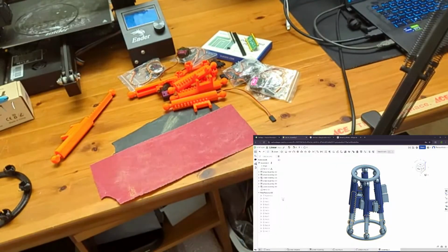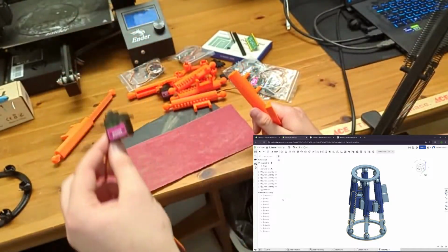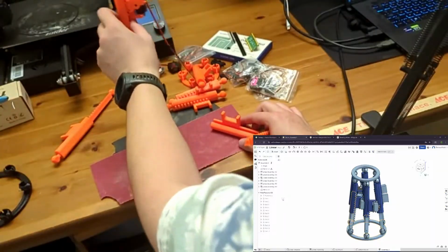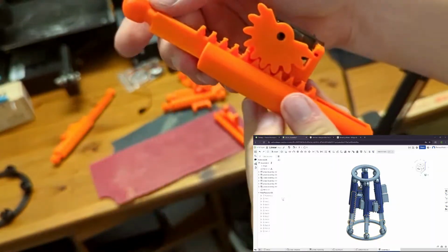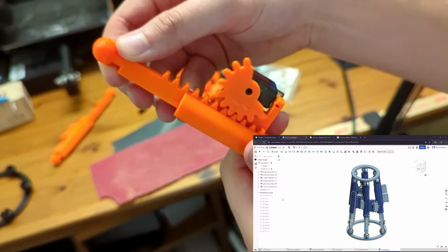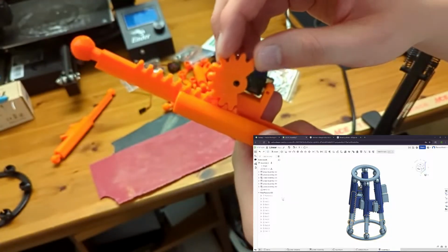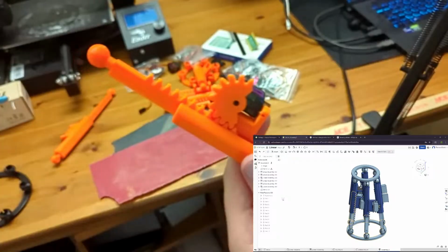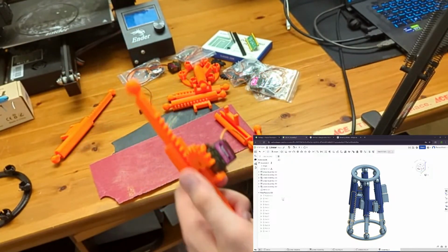The point of these is to act as linear actuators when I eventually attach these 9-gram servos to them. And you see I have one of these already assembled. So as it moves in and out, the servo spins, and it works the other way. If the servo spins, it'll force it in or force it out, and that way it can control how far the linear actuator expands, and thus the movement of the platform.